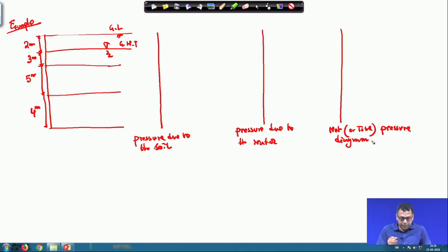Okay. So, first up to 2 meter we are drawing this and the values that are given for the layers, this is layer 1, this is layer 2, this is layer 3. For the first layer your phi value is given 30 degree and unit weight of soil is given 18 kilonewton per meter cube. So, as only 1 unit weight is given, we will consider that as the unit weight above the water table as well as the saturated unit weight.